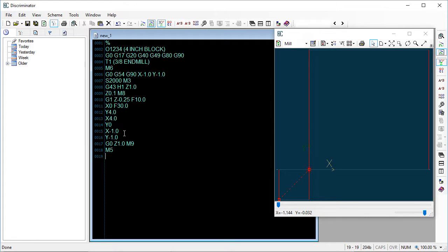Now, this one's a tricky one. G91, which is usually for incremental, not absolute. G28, Z0. This is telling the machine to get rid of the offsets for datum references and stuff and go to the machine home at Z0. So it'll send the tool right up. Okay?